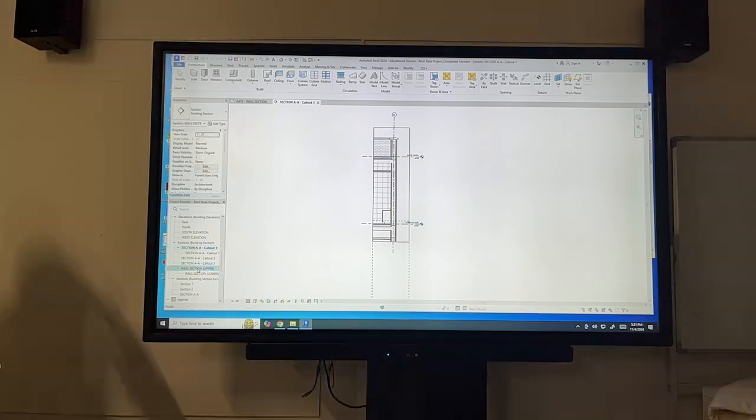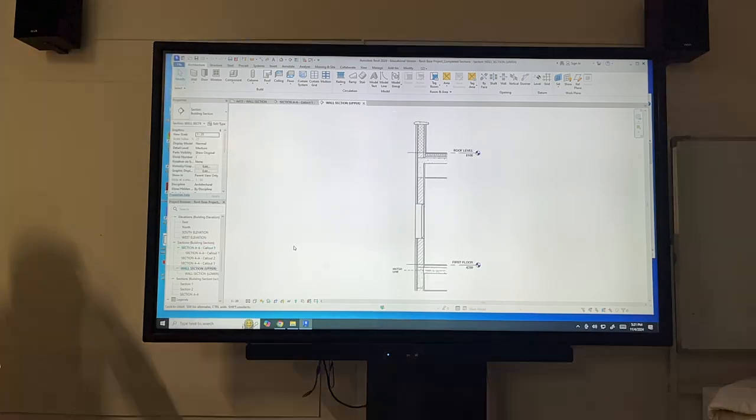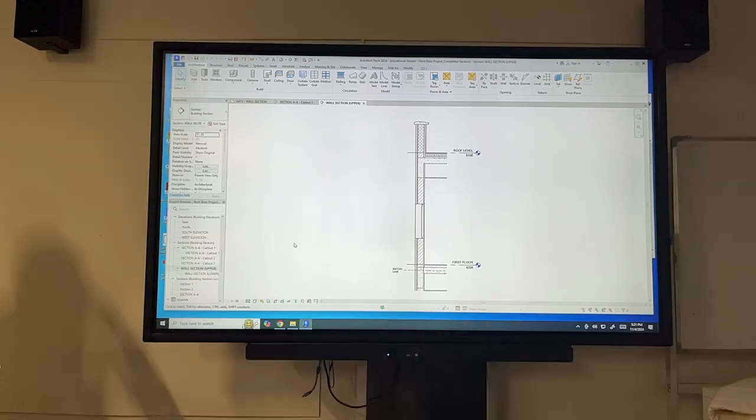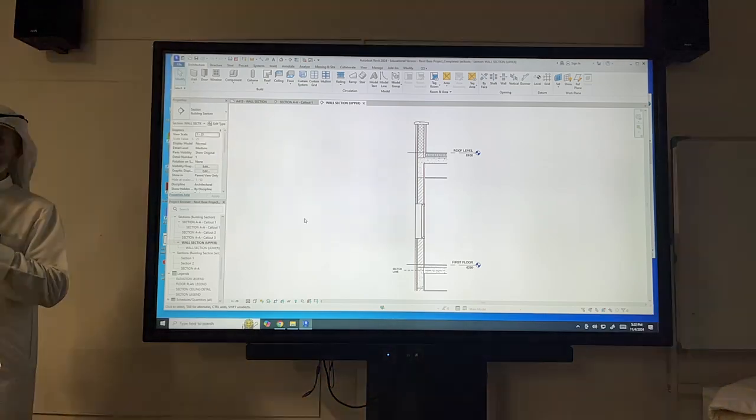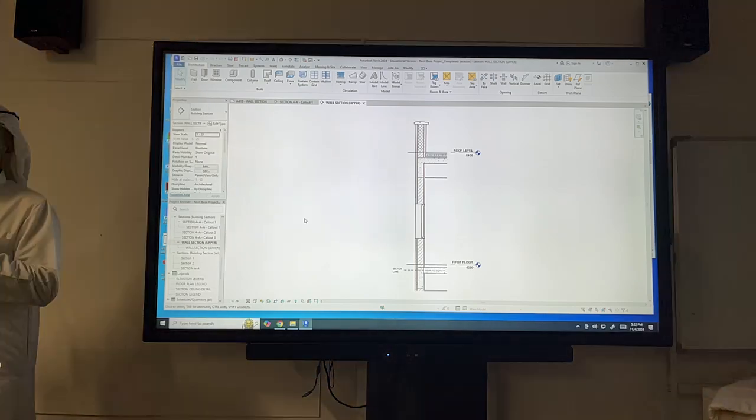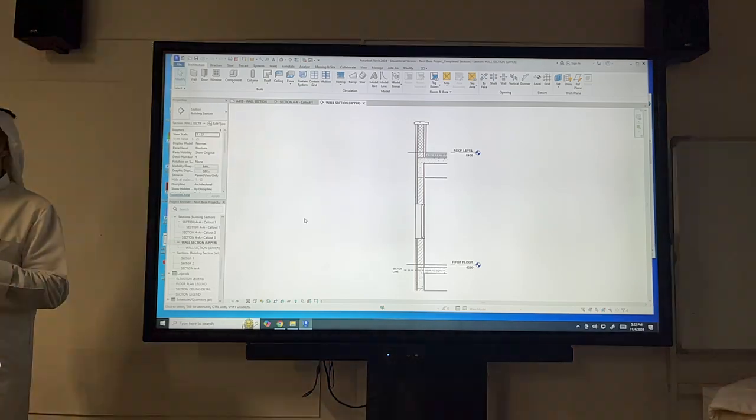Is this only for sections, or should all the drawings be dependent? Every callout, or just all the sections? No, it depends on what you want out of it. Usually dependent is because you're just looking at it from different parts, so you don't want additional details that are showing here but not showing here.